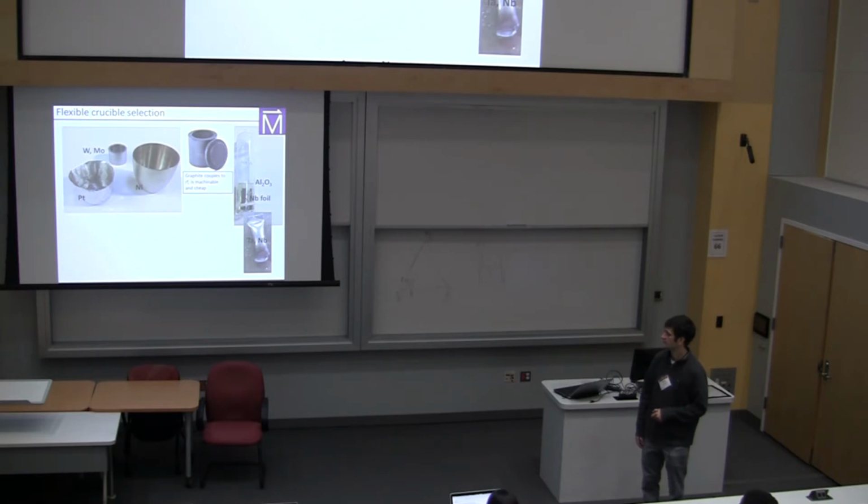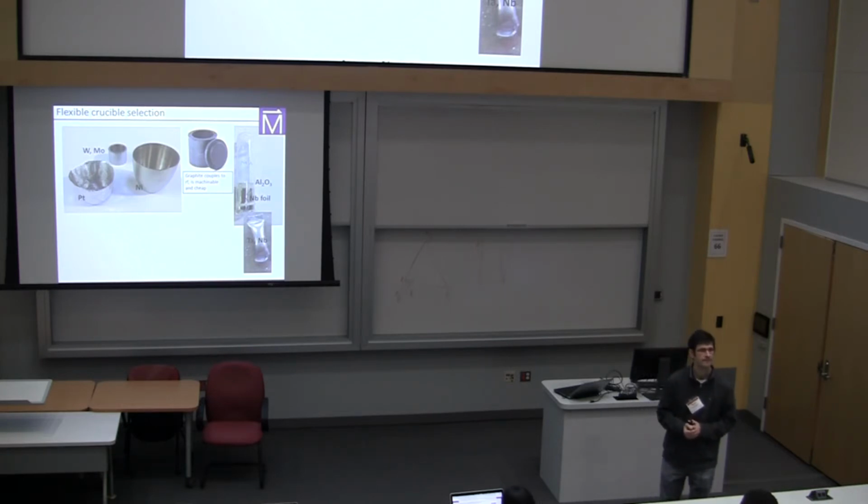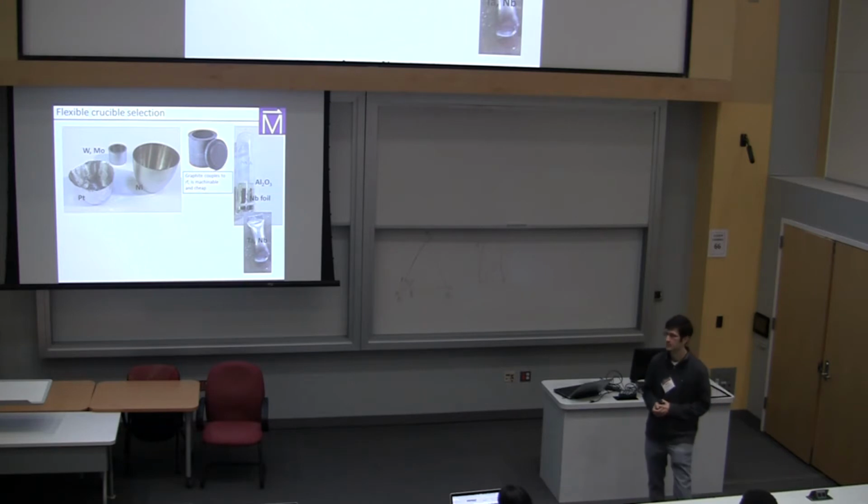But the graphite itself will go to 3000 degrees C or something like that. I'll tell you, I haven't heated it to 3000, but I've gone to like 1700, and its thermal expansion properties are very good as well. It doesn't crack itself, it just goes there and comes back. Can you put that in quartz? Yeah, you can put it in quartz, no problem.